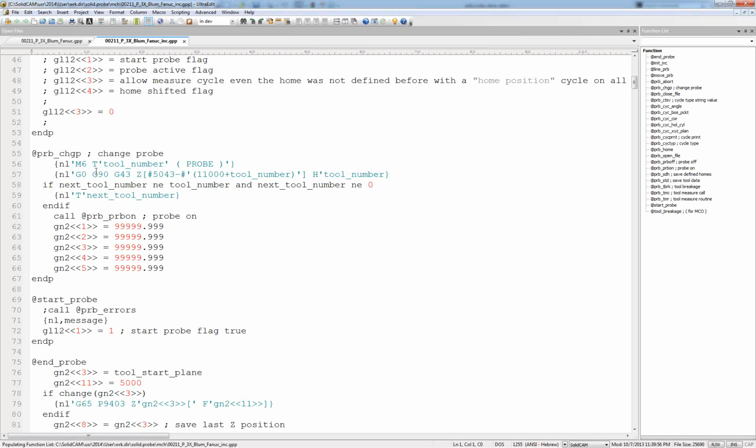because for the probe I want to take the tool length compensation at the tool change position. I change the tool automatically in this point, don't move anywhere. In this point you activate the tool length compensation. So I use some parameters to take the value on this place.